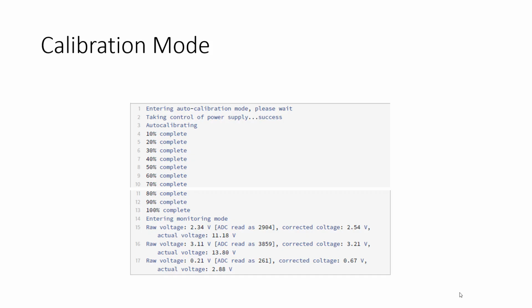If we were doing the actual project, though, I'd probably put a switching regulator on to regulate it down to 5 volts. So you cannot power the ESP32 off the VBAT input. Right. The VBAT input is used for the ADC. It's used for the motor connectors. These are motor connectors. And it's used for the sound, the speaker. So we have a speaker circuit, a motor circuit, and the ADC circuit on VBAT. Everything else is powered off of 5 volts, the USB 5 volts.